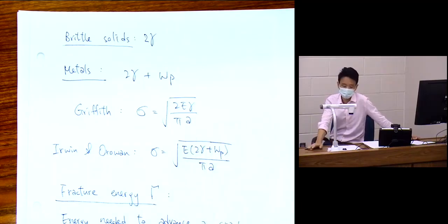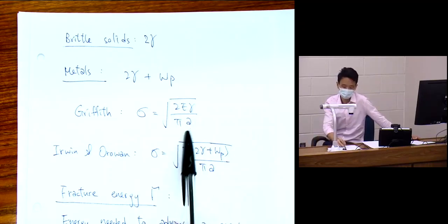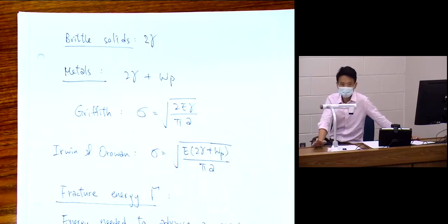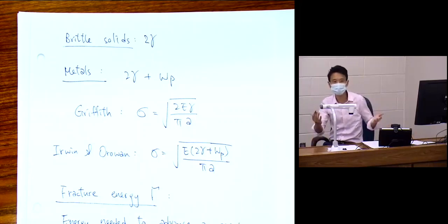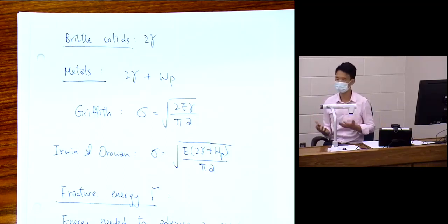So whenever we want to predict something or apply that formula to a piece of material that has a different crack length, then we always have to carry with us this a. Now, this is not convenient because we would like, for example, to compare two materials just in terms of the intrinsic resistance to fracture, right? So we want to get rid of that crack length dependence, because, for example, if we want to compare glass and steel,